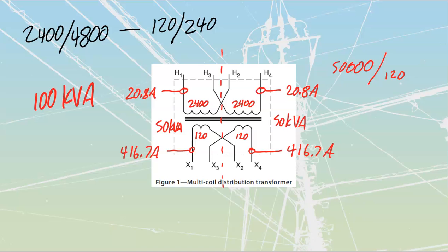Okay, let's start with connecting this thing into a high voltage bus. We're going to use this thing initially as a step-down transformer. It is more common for you to be using step-down transformers than step-up transformers. We're going to have a lot of installations where we're coming in at a higher value of voltage. 600, 347 is pretty common in the industrial and even in light commercial type of applications.